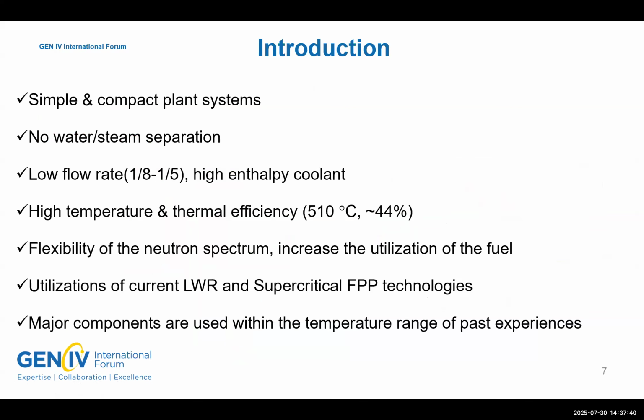It only has one loop. They didn't need the secondary loop and steam generators like BWR. And also you will see that because when the water is in the supercritical condition, there is a one-phase flow. So in the one-phase flow, we don't need the water-steam separation, and also you can see that the thermal conductivity